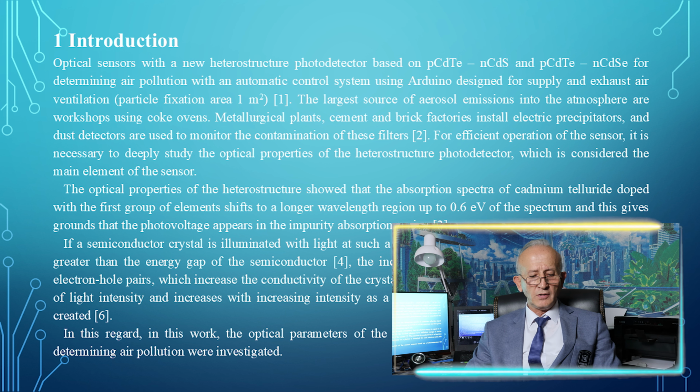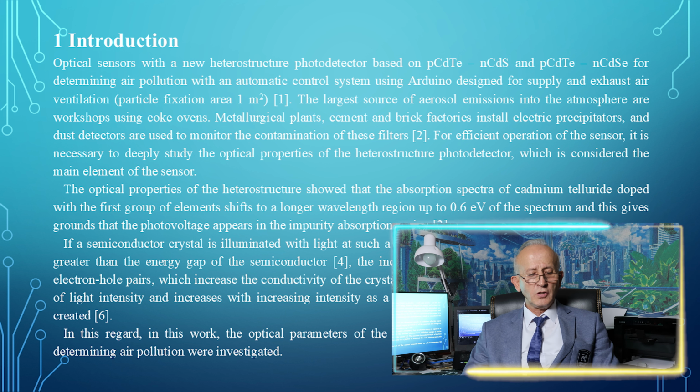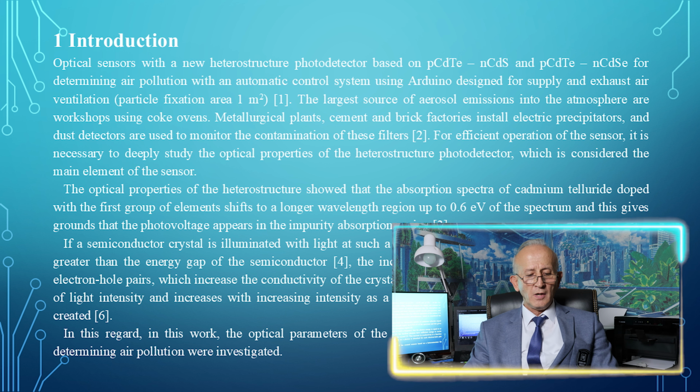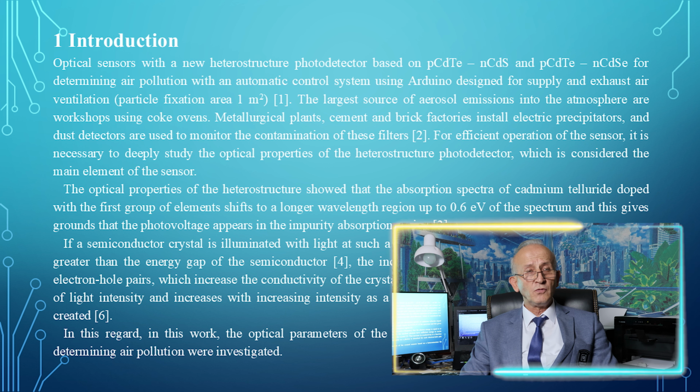If a semiconductor crystal is illuminated, this light has such a frequency that the photon energy is equal to or greater than the energy gap of the semiconductor. The incident photons have sufficient energy to excite electron-hole pairs, which increase the conductivity of the crystal. This increase in conductivity is a function of light intensity, as a photon is absorbed for each electron-hole pair created. In this regard, in this work, the optical parameters of the created sensors based on the heterostructure for determining air pollution were investigated.